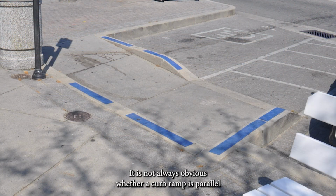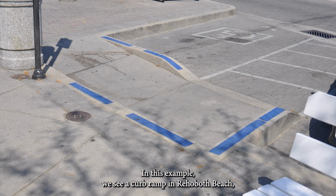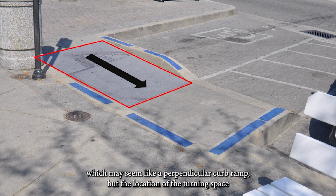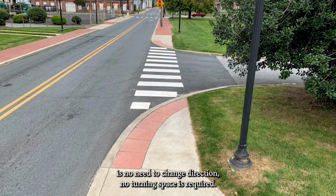It is not always obvious whether a curb ramp is parallel or perpendicular. The orientation of the ramp segment and the location of the turning space are key elements in defining the curb ramp type. In this example, we see a curb ramp in Rehoboth Beach where the ramp segment is built up to the curb, which may seem like a perpendicular curb ramp. But the location of the turning space at the bottom of the ramp segment gives it away as a parallel type curb ramp. Where there is no need to change direction, no turning space is required.